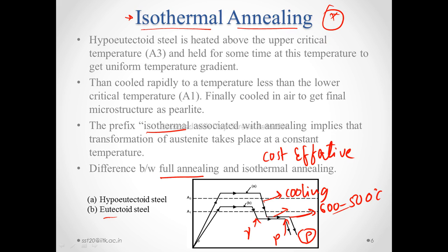This process not only improves machinability in general but also results in a better surface finish by machining. The process is of great use for alloy steels, as these steels have to be cooled slowly.